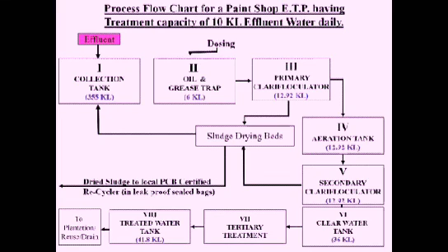We can then have the treated water tank installed after the tertiary treatment, wherein we can collect the treated water and reuse it for plantation, our canteen utility, utensils washing, or reuse in any of the factory utilities, or we can put it in the drain also. In case we are putting this water for the plantation, irrespective of whether we are checking the norms daily of the clean water from ETP or STP, we must get a periodical testing of the soil also, wherein we are sending this water for plantation.